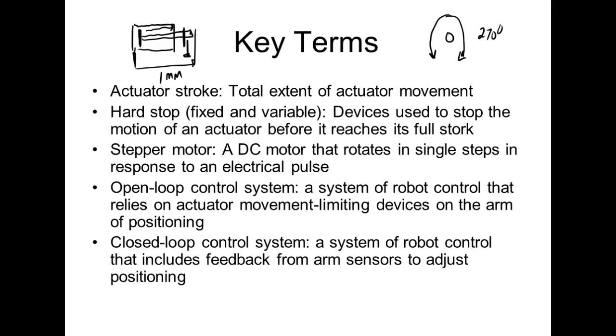the points are not done in a program with a bunch of instructions, especially the pneumatic robots. It's done by doing what? Going out there and moving these hard stops. Now you still have to have a controller because it's still got to decide which axis to move, right?